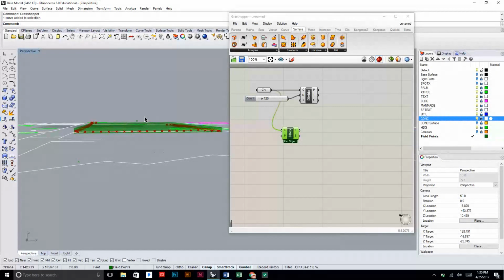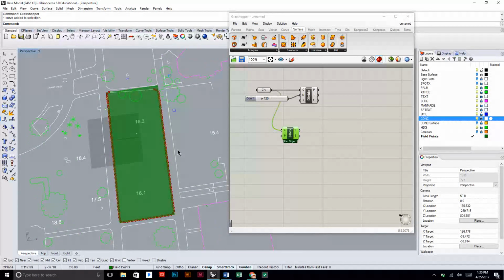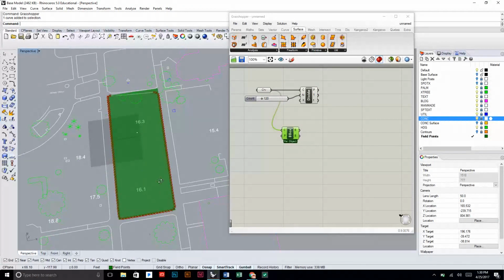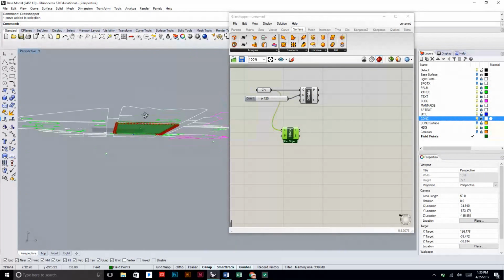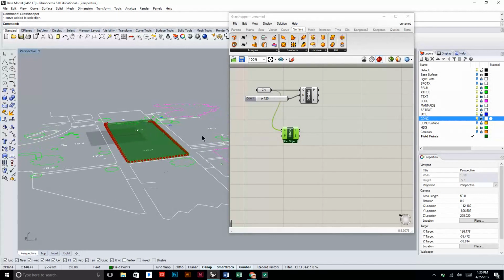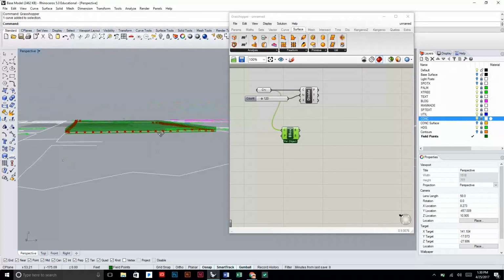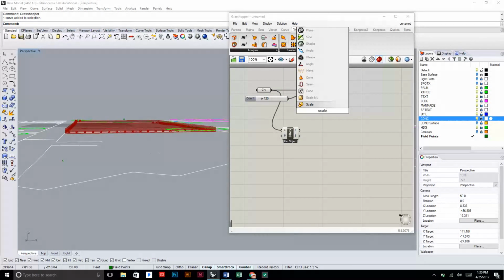So it's going to allow the forces to go not only horizontally within our site, but also vertically, so we can actually have our forces start to go on the z-axis. But in order to do that, we need to give it a little bit more space. So we're going to scale our bounding box in the z direction. I'm going to start typing scale, and I'm going to select Scale NU, the non-uniform factors.